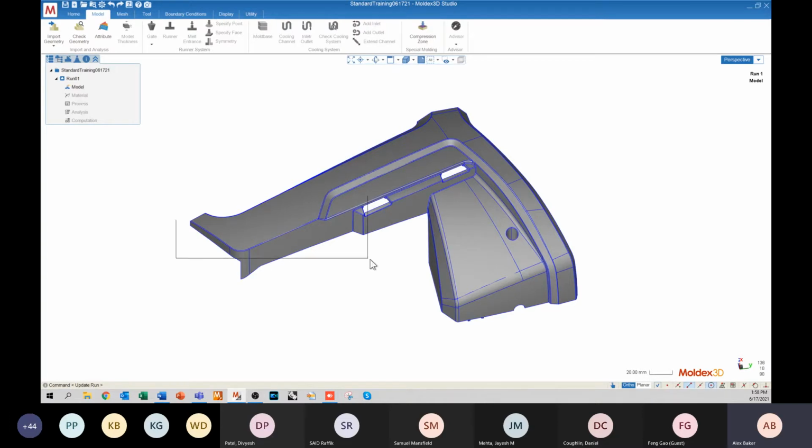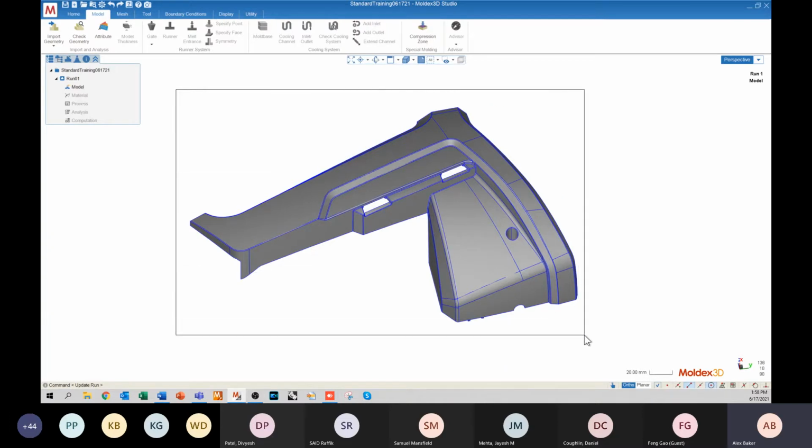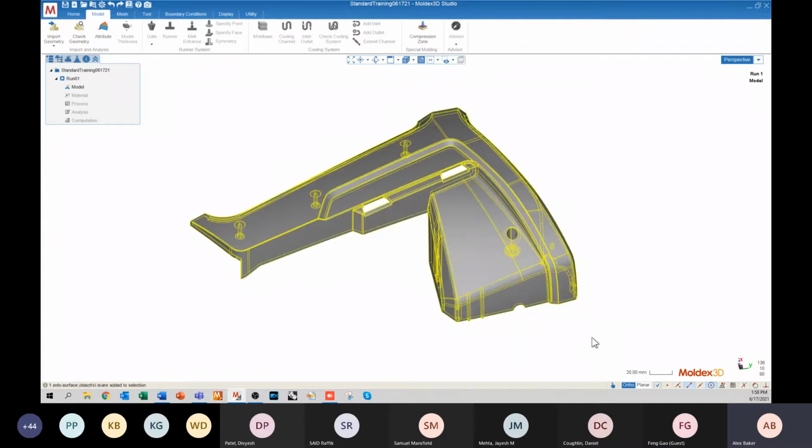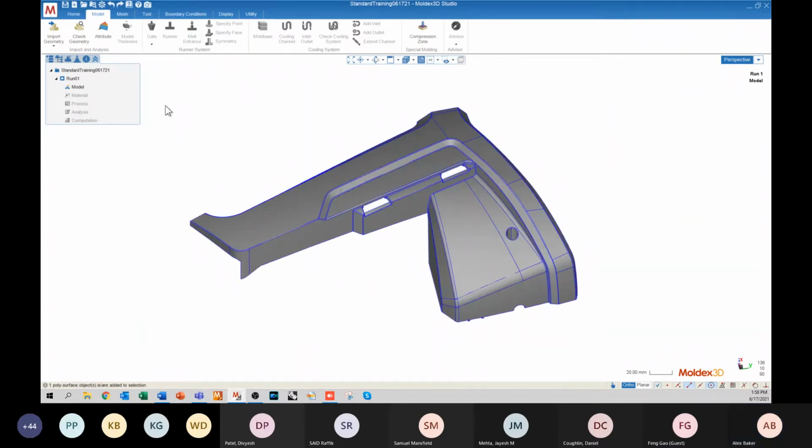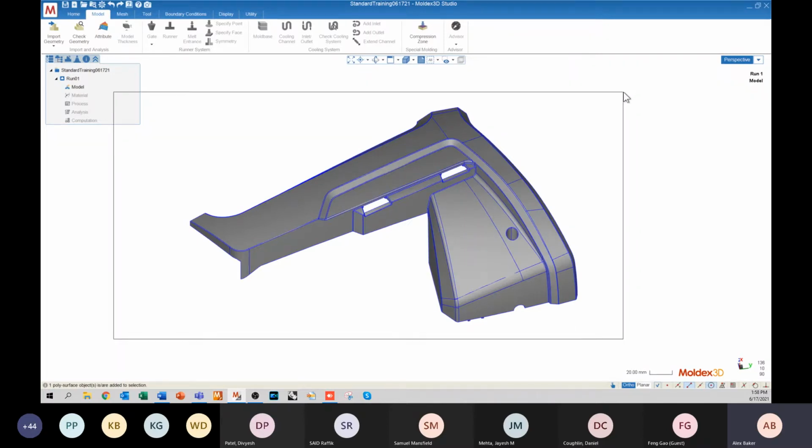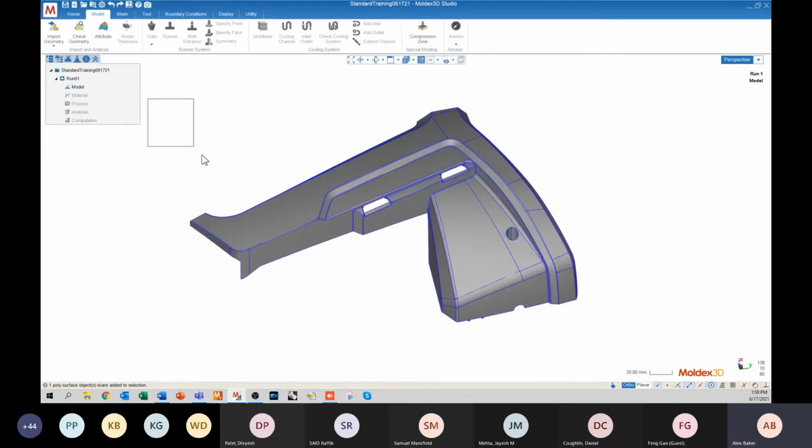And if you left click drag from left to right across your screen, this box will select anything that is completely encapsulated within the boundaries of the box. All right, so if I don't get my whole model, it's not selected. And you can see that you can even go from the bottom of your screen to the top of your screen as well.